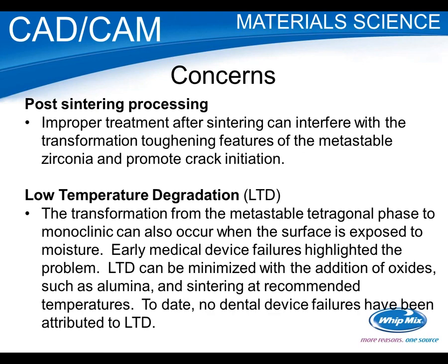You'll see that the zirconia used now for medical and dental has alumina in it, and that helps minimize the low temperature degradation. But I'm going to hit on this again because we'll see that in our processing we can also worsen this. Now, I do want to make a note that it depends on who you talk to how severe this is.